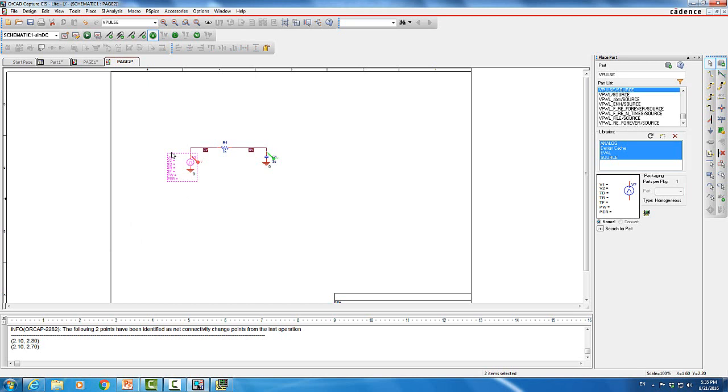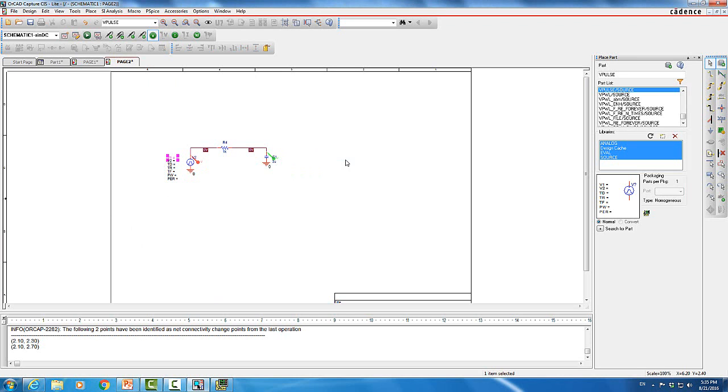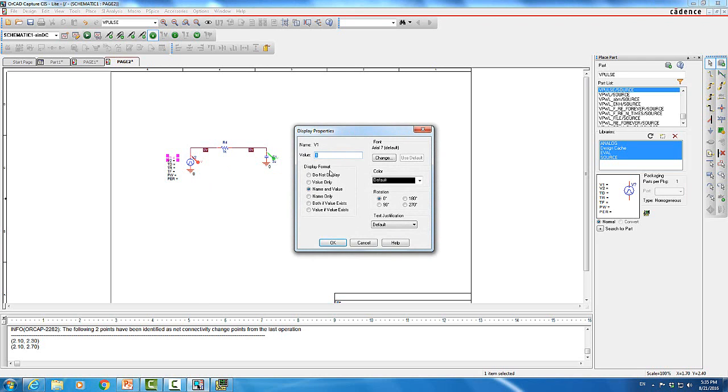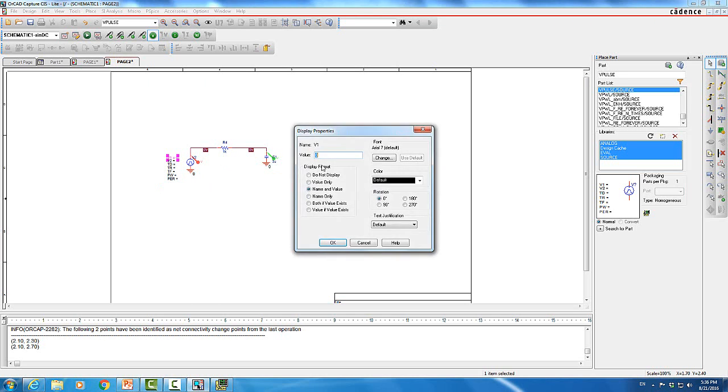We have a lot of parameters here we need to add, so we have to be careful with what we add. The first value here will be V1. That's going to be the initial voltage that you're going to have for the rectangular pulse. The rectangular pulse will continue generating voltages as rectangular waves forever, right? So we call them rectangular pulse. We're going to start with a value 0, so let's make sure that the initial value is 0. The second value is going to go to 1 volt. So this is in a way a unit step function.